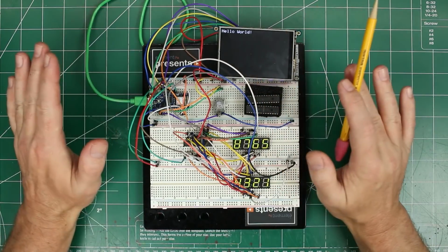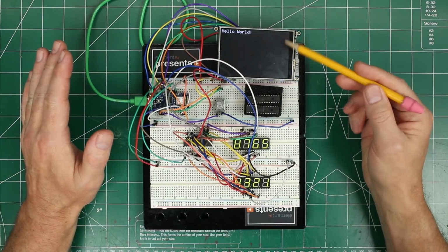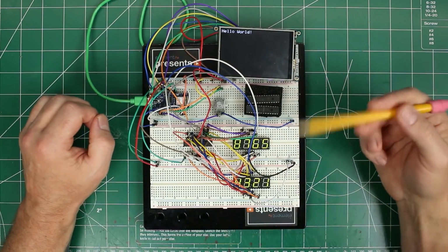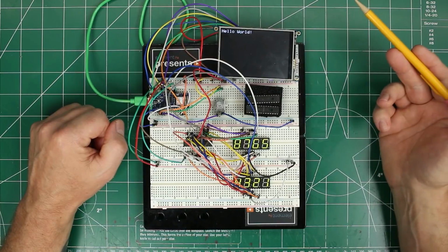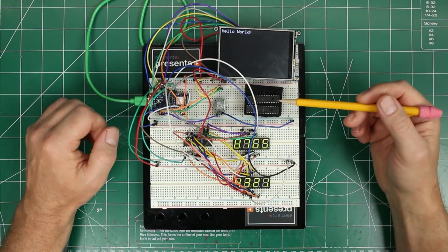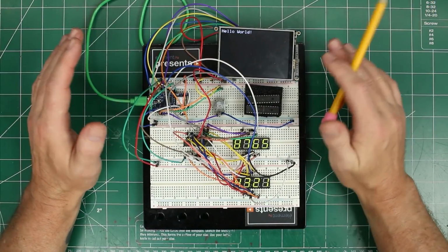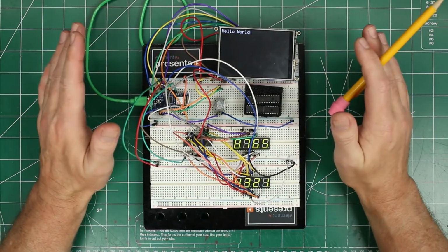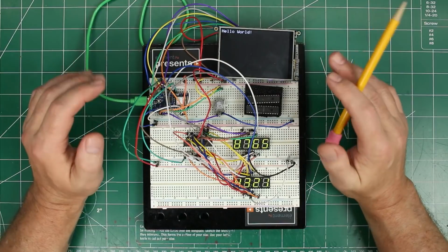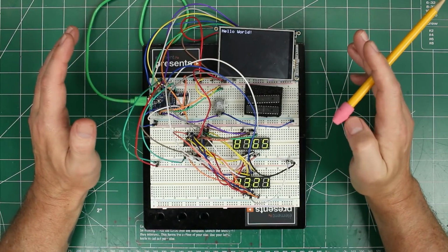It just stops the Arduino completely until it's done scanning through, and then the Arduino picks up again. I checked in with the Adafruit people, and without significant changes or completely rewriting the library, it's unavoidable. It is blocking. There wasn't a way around it. At least that's what they told me.